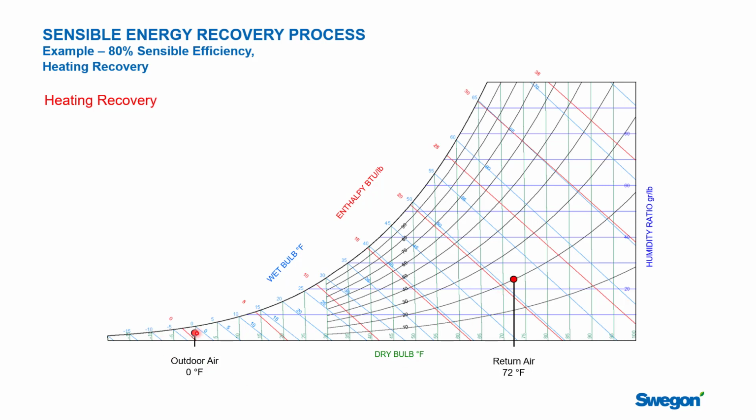So in this case, we're going to start with air that's at 0 degrees dry bulb. So you can see this is a low temperature psychrometric chart, goes way out into the low end, and we're starting at 0 degrees Fahrenheit. This air is very close to saturation. Winter air does not hold very much humidity because it's cold. It's not capable of holding a lot of humidity, and so it's always very close to saturation, that being this curve here.